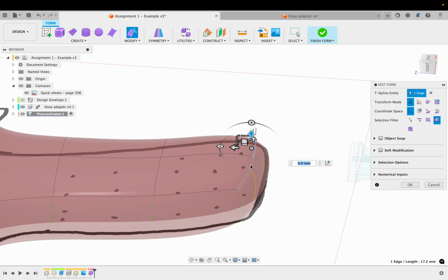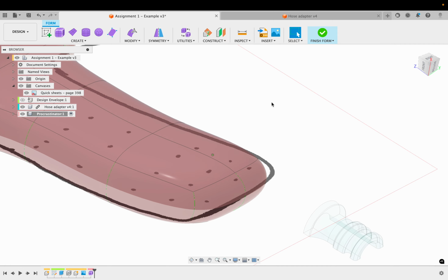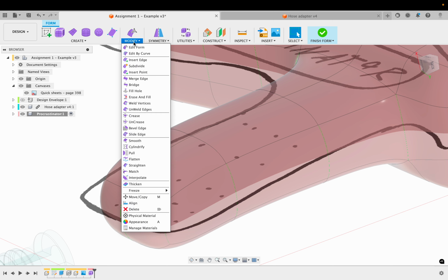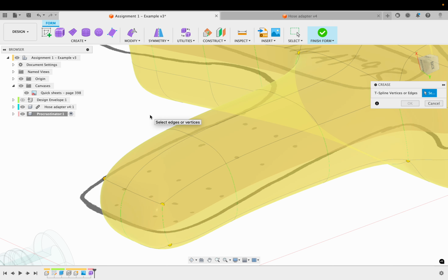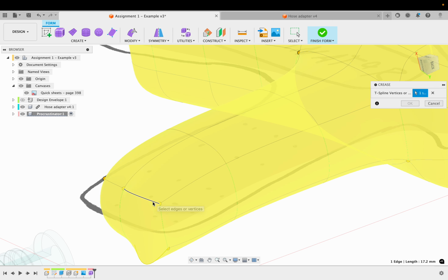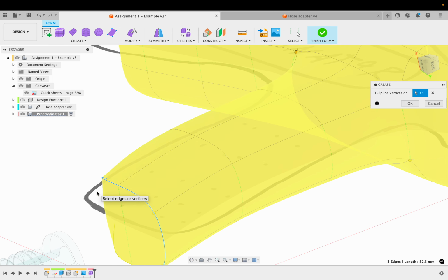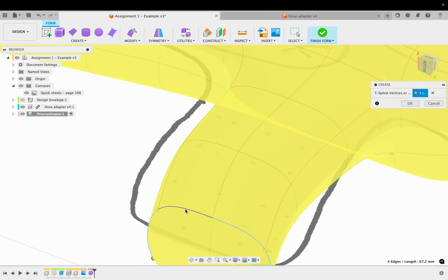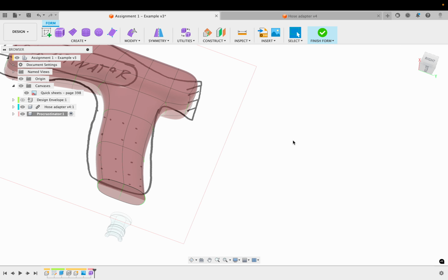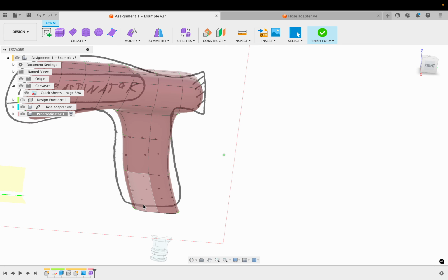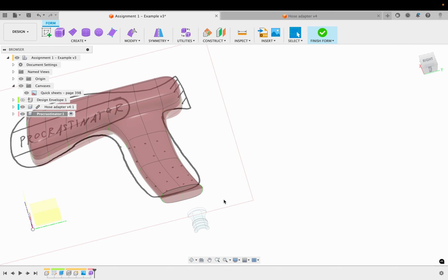So if I want to make a corner tighter, I can do a couple of things. I can use a function called crease. So if I do crease, let's see, here. Essentially that will just make a sharp corner where you use the crease. So if I do it down here, maybe that's a good start. Actually, that didn't look too bad. So now I used crease, and that just broke off tangency in that area, which could make sense when I have a hose connector.